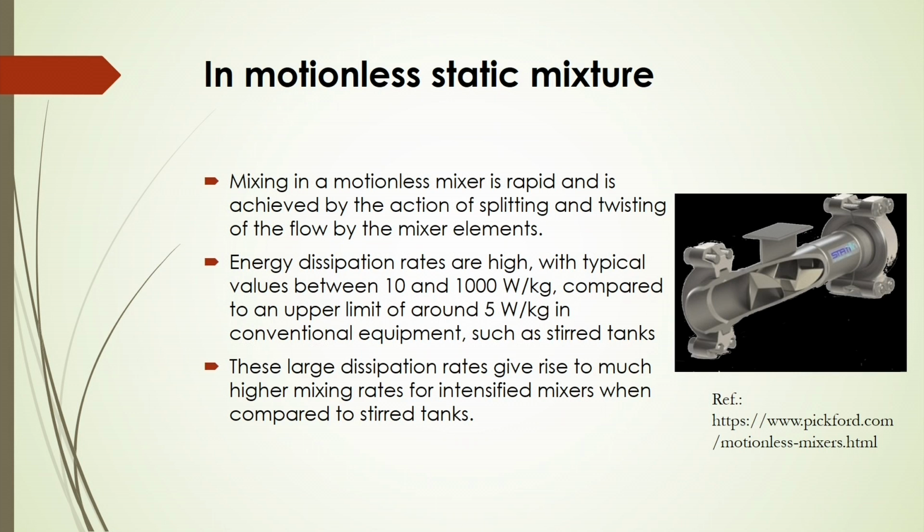It may be 10 to 1000 watt per kg, and also you can say that some other conventional equipment can be used to produce that interfacial area, but that will not be comparable with this type of static mixer, because this static mixer may give you higher energy consumption, but it may give you more interfacial area compared to the other equipment where less energy is consumed, like stirred tanks.